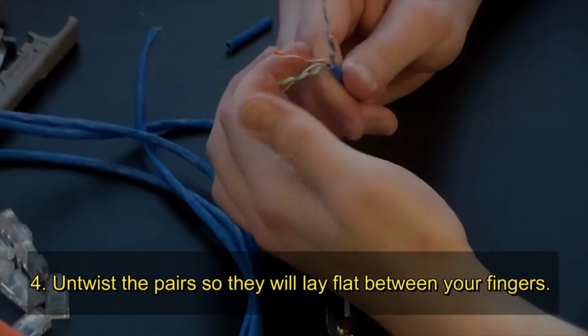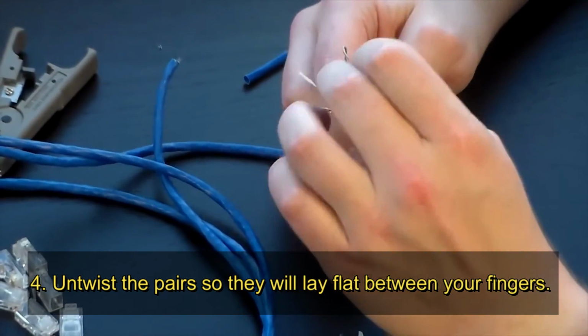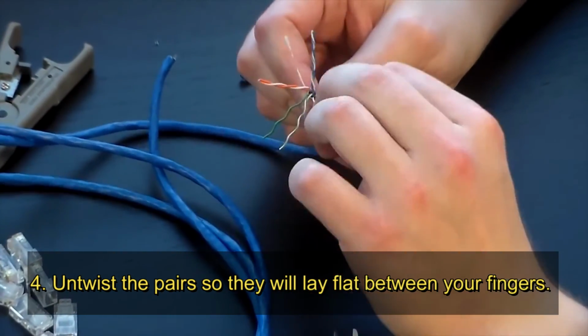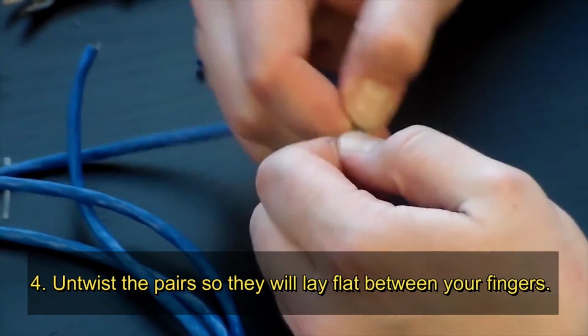Step number 4. Untwist the pair so they will lay flat between your fingers. The white piece of thread can be cut off even with the jacket. For easier handling, cut the wires so that they are 3/4 inch long from the base of the jacket and even in length.